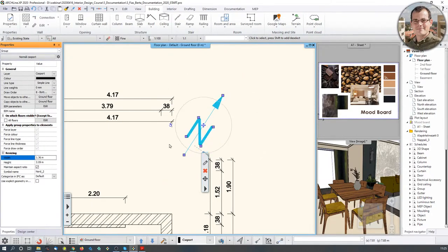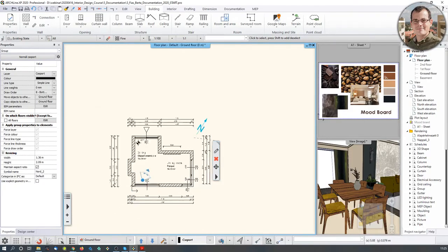Hit enter, and the software scales the group the way I want. So again, if you have any element and you want to change its size, you can add multipliers or divisions or anything like that. Formulas work here perfectly. Okay, having said that regarding the signs and symbols, let's proceed now with a text.